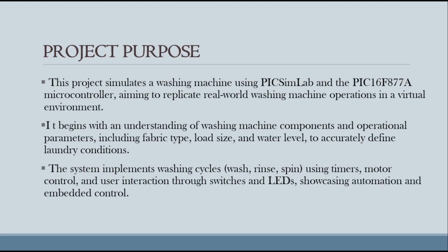Now let us see the purpose of the project. This project simulates a washing machine using PicsimLab and the PIC16F877A microcontroller, aiming to replicate real-world washing machine operations in a virtual environment. It begins with an understanding of the washing machine components and the operational parameters, including fabric type, load size, and water level. To accurately define laundry conditions, the system implements washing cycles using timers, motor control, and user interaction through switches and LEDs, showcasing automation and embedded control.